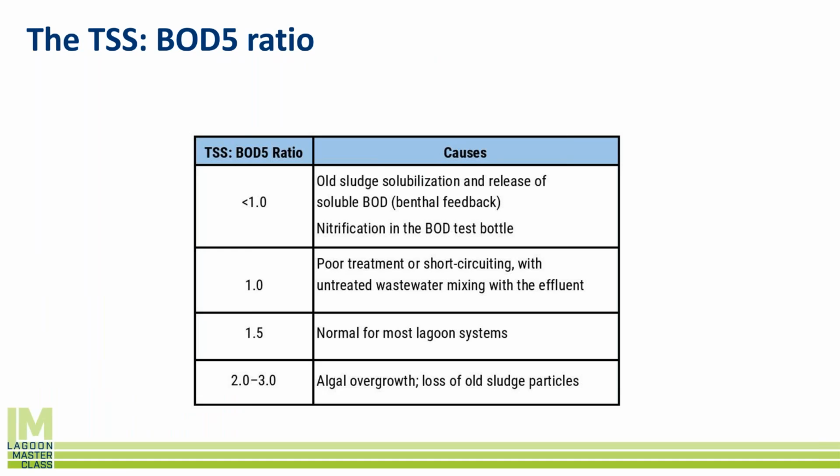So are you getting nitrification in your BOD test? One of the things you want to look at right off the bat, if you're taking a BOD test, is your BOD low enough in your BOD bottle that you're actually starting to see nitrification occur in the bottle? And that's actually what's causing your BOD to go up. So it could be a testing issue.